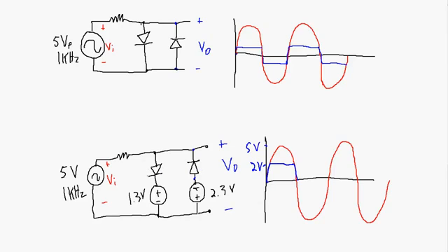In the negative half of the cycle, of course, this diode will always be reverse biased, so no current will be through this diode. But it's not until at a minus 3 volt input that this diode becomes forward biased, so current will go through that, so we're going to have clipping at that minus 3 volt point. So no clipping, no clipping, no clipping. At minus 3 volts we have clipping. So right at that point we're going to be at minus 3 volts.